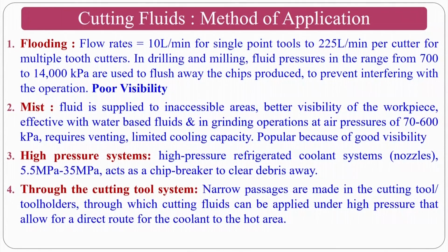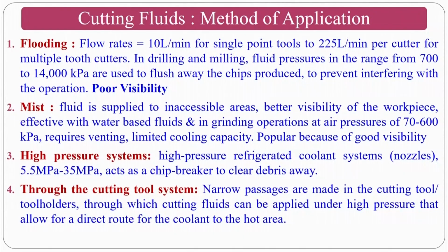Another one is mist application, where you can mix the cutting fluid along with compressed air, and you can mix in two ways. One is internally you can mix, or externally you can mix, then you push it towards the machining region or the grinding region. Then high pressure systems you can use. Here there is no requirement of air, but you send high pressure cutting fluid into the grinding region. This is some other, in a single point cutting tool or a multi point cutting tool like a milling cutter and other things. The fourth one also refers to making internal holes in a cutting tool, but it may not be possible in grinding.